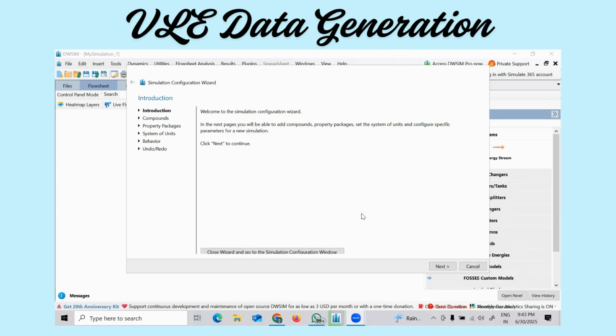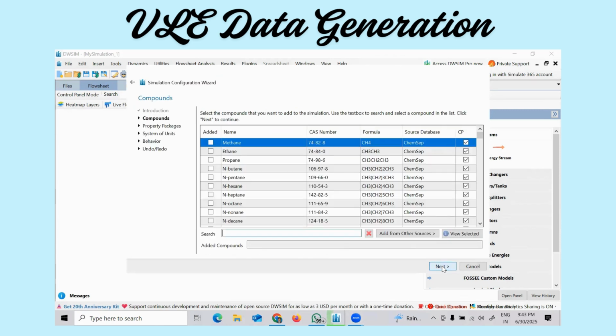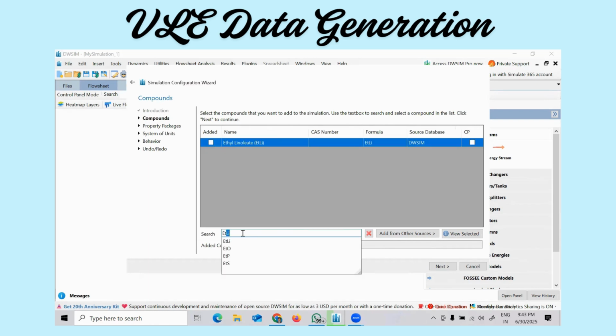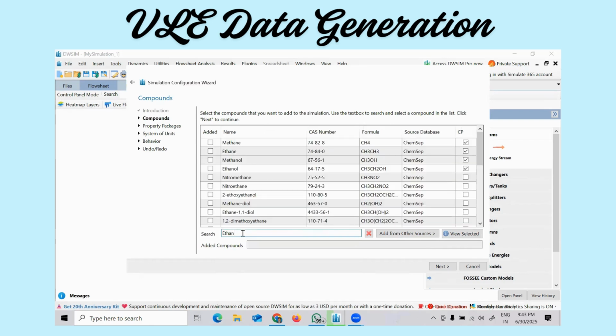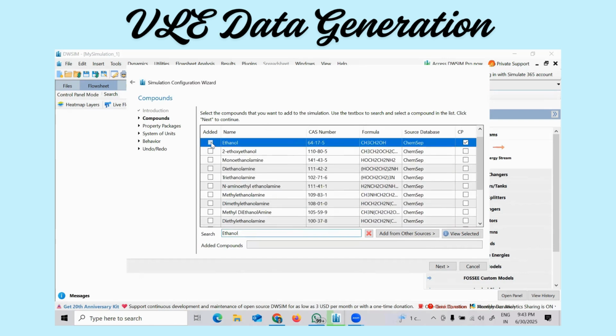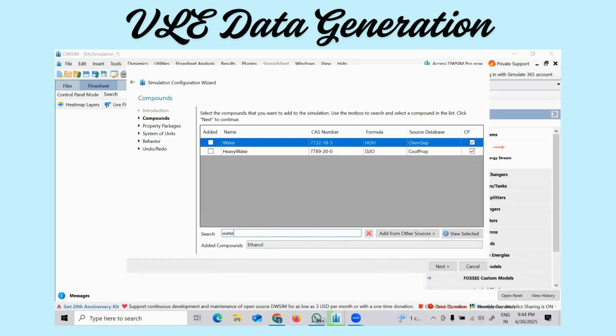I'm going to go further, next, and then this is the compounds wizard, wherein I'm going to take up two systems, that is, two compounds. Number one is ethanol, right? So this is the component which I'm going to add. Now you can see the added component is automatically shown as ethanol. Next I take up water and then I click this particular checkbox as getting added.